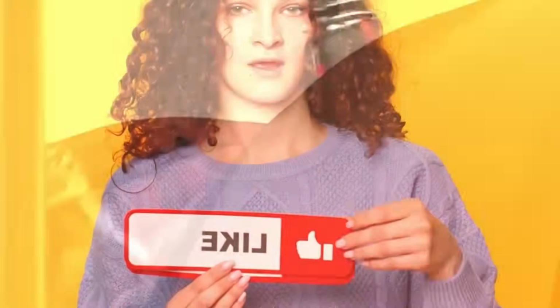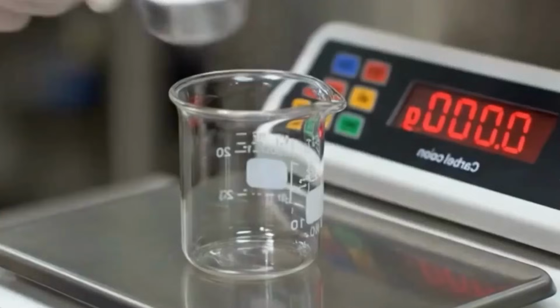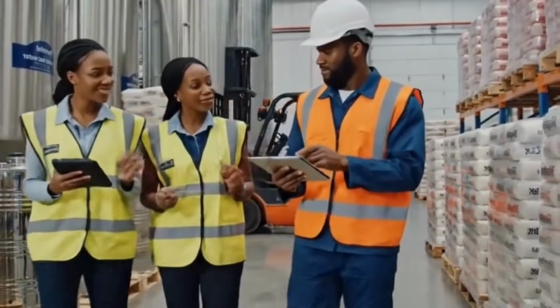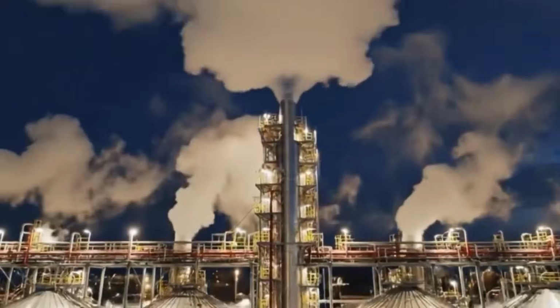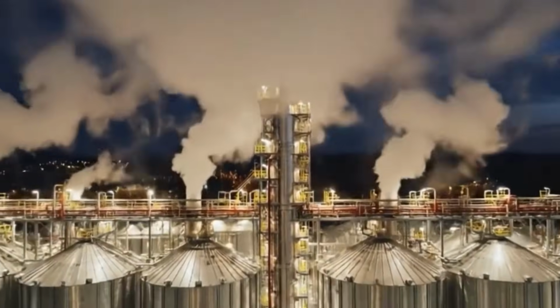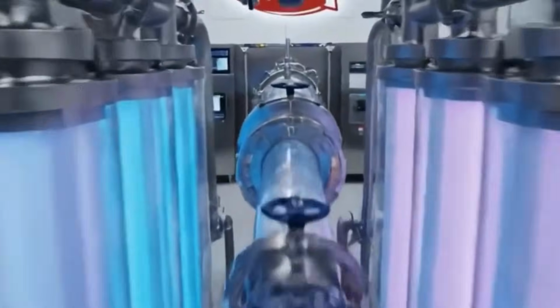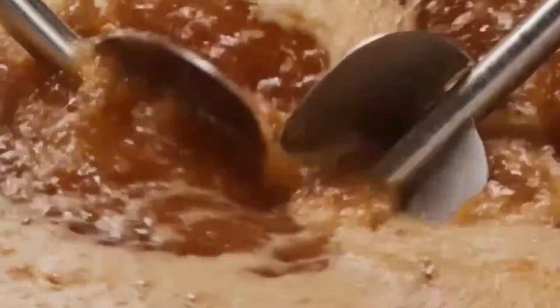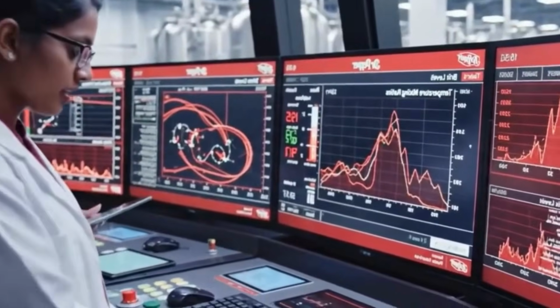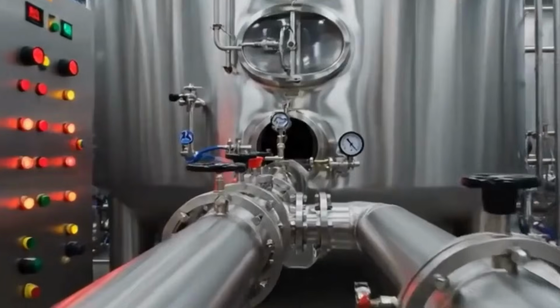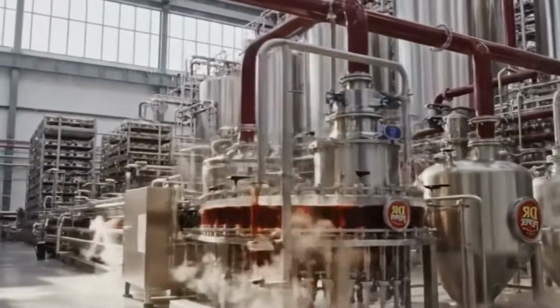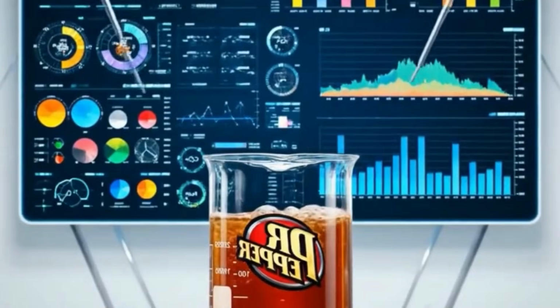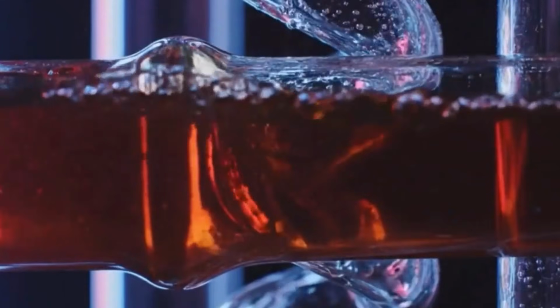Labeled products travel to the packaging area. Containers are grouped into multi-packs using high-speed collators. For bottles, robotic arms or pneumatic sweepers push groups of 6, 12, or 24 into cardboard carriers or plastic overwrap. For cans, shrink film machines envelop the groupings with polyethylene film. The packs pass through shrink tunnels, where the film tightens around the cans. Heat is applied via convection blowers at calibrated temperatures to avoid deformation.